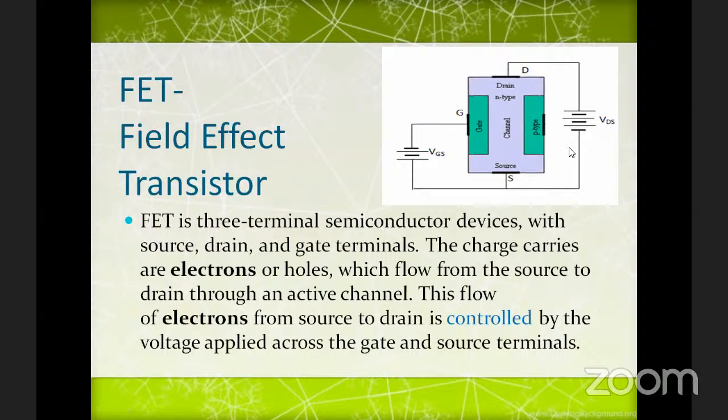Therefore, this has helped in implementing the ion selective field effect transistor, also known as ISFET, the ion sensitive field effect transistor. This is an advantage compared to the conventional type of electrode, which has to use two electrodes, a reference electrode and a measuring electrode, whereas the ion sensitive electrode has a single integrated microelectronic system.